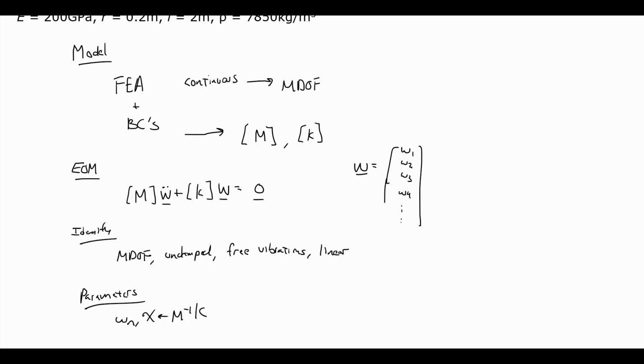But we want to keep in mind that the boundary conditions are going to eliminate some of our degrees of freedom, or that is to say, we know that those degrees of freedom are always going to be 0, so we're not going to need to solve for them. So we'll come back to this equation of motion step to remind ourselves of that. But another thing is that our odd W's are displacements or deflections, and the evens are slopes.